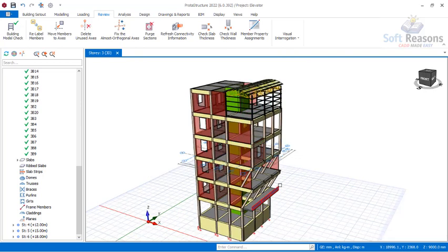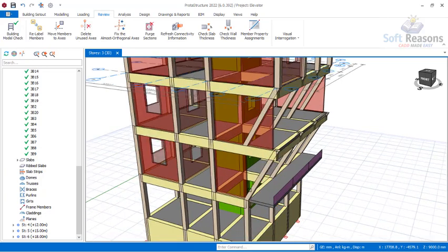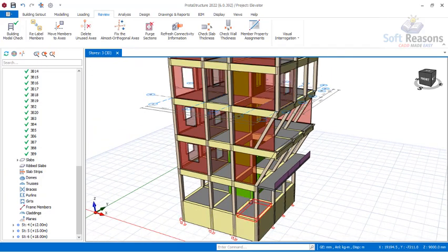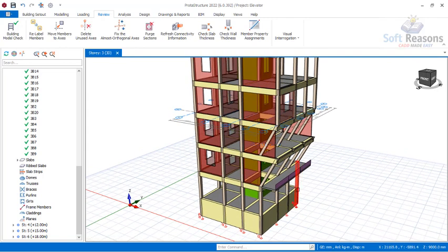And again, sparse solver error also comes up when you have most of these inclined members. Okay, like the slab, if you try to create a slab in form of a stairway. That is why most of the time you see in our design, we don't provide that slab that looks like a stairway, okay, because it causes that sparse solver error. So you just have to neglect that in your design.